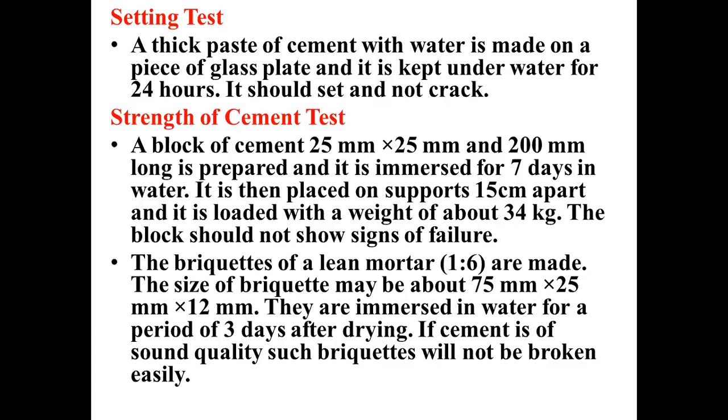So with the given loading conditions, this is another form of test we are going to conduct to know the strength property of the cement. One is the block we are going to prepare, and another is the briquette mold, prepared with irregular shape and size, and we are going to test it after 3 days. So this is about the quality of the cement using the strength and setting tests.